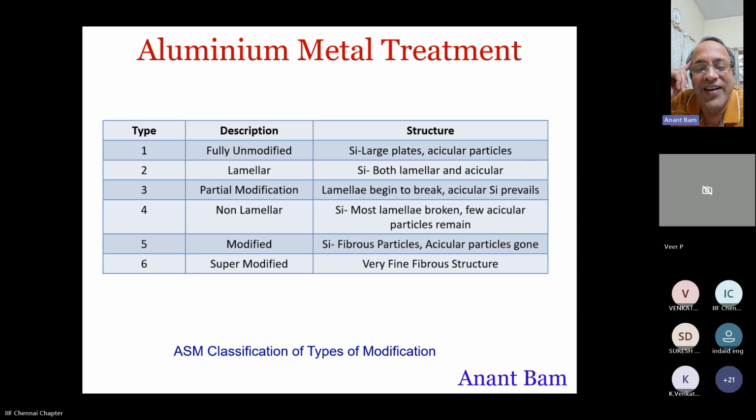Okay. Let me tell you that usually 2.5%, 4%, 5% are the figures expected from the test bar for elongation of A356. But with proper modification, I have witnessed 19% to 23% elongation from the test bar with a UTS of 480 up to 530 megapascal.